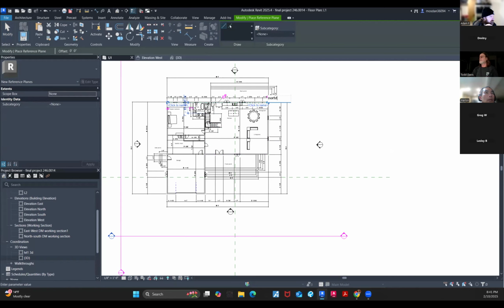These names don't really matter when you have just 1 or 2 or 3, but when you get more than 10, you're really going to wish you named them better. All right. Go ahead and hit enter, and that'll set that plane. So what we've done is we built a plane in space that we can use to follow or extrude upon. Okay. So now I want you to hit escape.